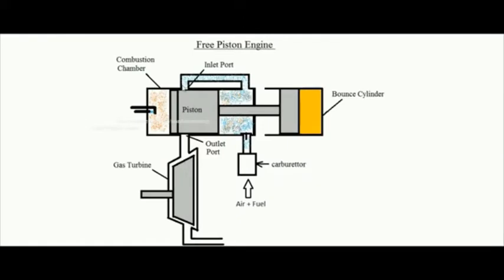It has only one way through which it can go out, that is through this inlet port via this transfer duct, but the piston itself is acting as a blockage. This compressing charge behind this piston has only one way to escape, through this transfer duct and this inlet port. But we can see that the piston itself is a sort of blockage in this inlet port. Yes, see, whatever charge is compressed behind this piston can come out through this inlet port, which is connected by a transfer port, because this non-return valve doesn't allow the charge to go back, but this piston itself is closing this inlet port as well as this exhaust port.